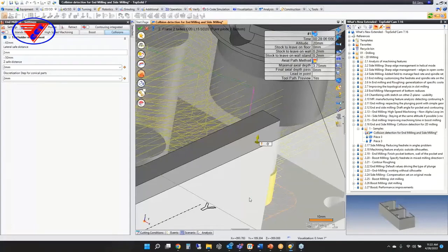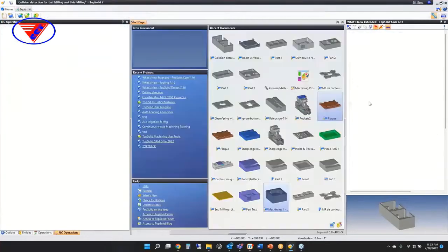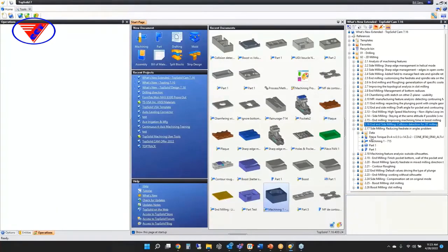The spun profile is as simplified as possible, because if you have a really complex profile for your tool definition, it's going to add to the calculation time. So just keep that in mind. If you turn this option on and it's taking a long time to crunch out for you, go back and check your tool definitions, specifically your holder definition, to make sure you don't have a lot of crazy extra curves in there that you don't need. And obviously, if you have issues, reach out to support. We'll help guide you through it. Perfect.